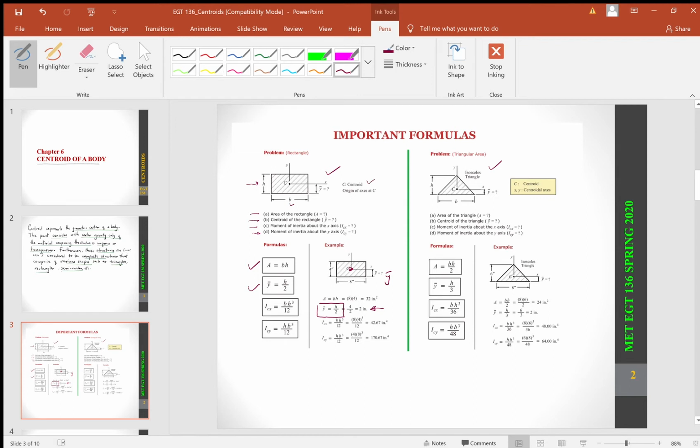Okay? So again, for a composite body, in particular this rectangular shape, if you want to find the centroid, our centroid is denoted from the x-axis. Now this is our x-axis right here, and this is our y-axis right here. So if you want to locate the y bar, as we call it, that's going to be a distance from the x-axis to the centroid. It's nothing more than a distance. It's going to be the height divided by 2, and that's what you see right here.